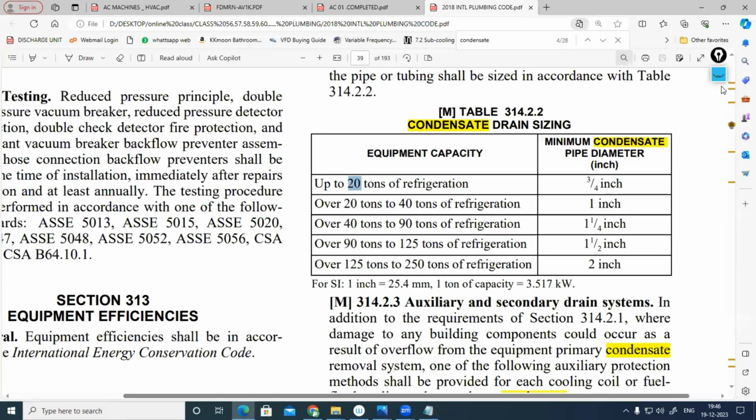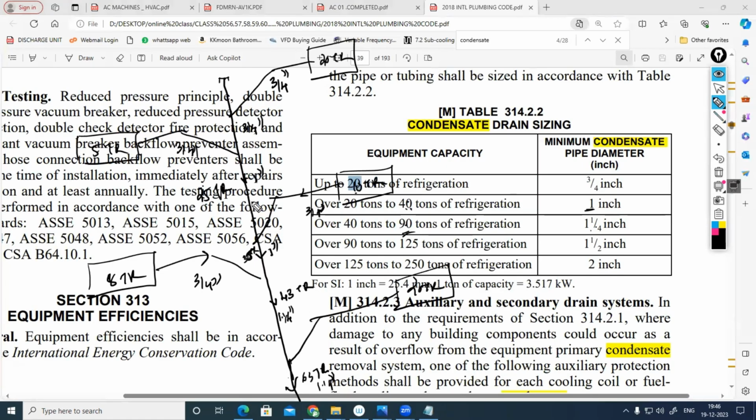If you want to find that in mm, the type of pipe material, the proposed material by ASHRAE is Schedule 40 PVC plastic only. Schedule 40 is a number. If the schedule number is increasing, means the wall thickness of the pipe material will increase. Okay, schedule number. And this is called a nominal pipe size, NPS. Nominal pipe size or diameter nominal. Nominal pipe size is in inches, diameter nominal is in millimeter. It's a representative value only.